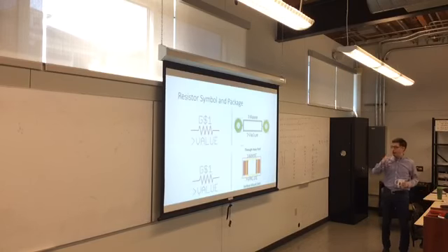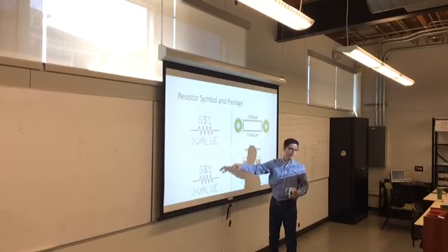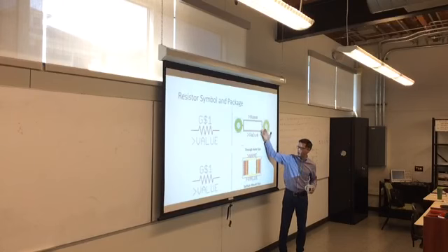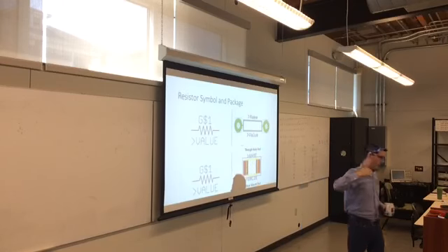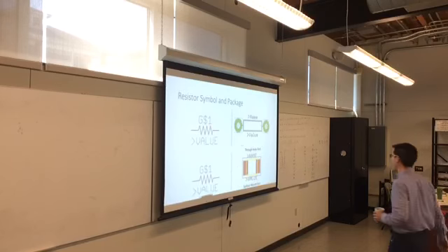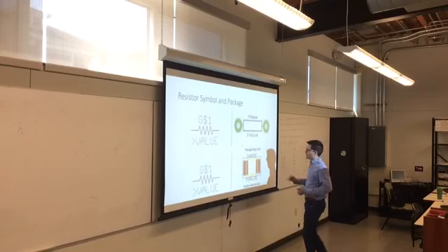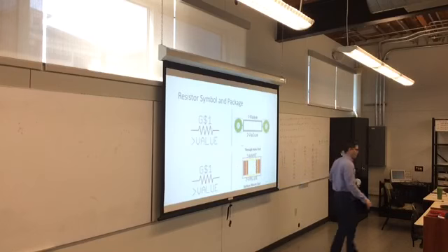Same thing with a resistor. On the schematic, a resistor can look like this, it can look like this. That can either imply a through-hole part, or it can imply a surface mount part. So if you see these symbols on a layout, these are drill holes or these are vias. So that green symbol means someone's drilling through the board, there's a hole there, that hole is there to connect to different layers, or it can be actually just a drill hole. This is a little tiny resistor with pin pads on either side.